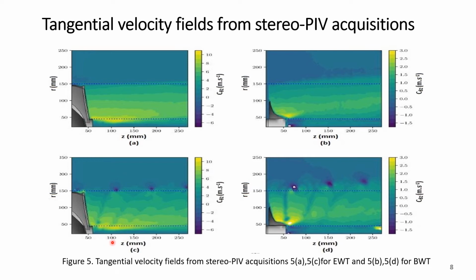For example, at distance z equals 111 millimeter, the velocity at the vortex center is 6.8 meter per second, and it decreases from 6.8 to 5.6 meter per second for the second vortex center, and then from 5.6 to 4.8 meter per second for the third vortex center. The wake angle is 3 degrees, and no recirculating bubble associated with vortex breakdown has been observed in the 500 millimeter downstream. Also, the radial distance between the vortex and the rotor axis decreases by 2 millimeter for each center.